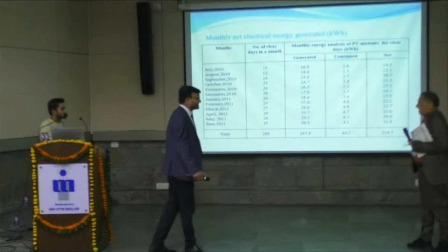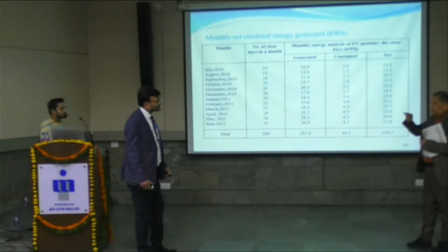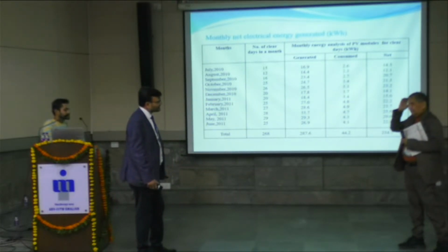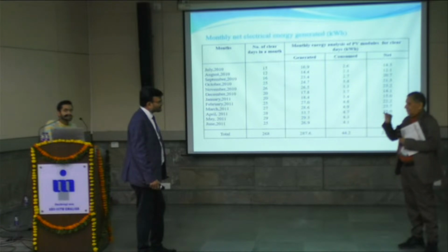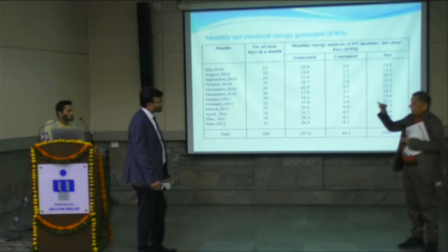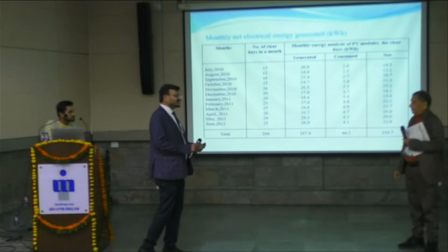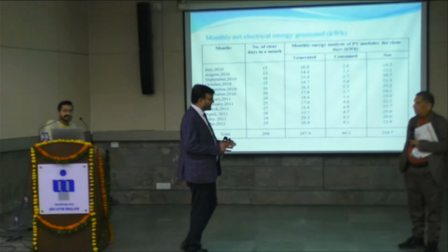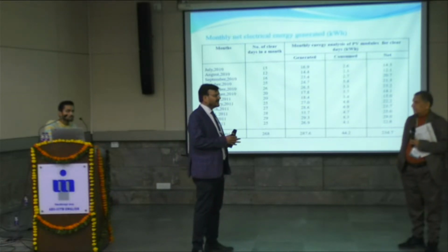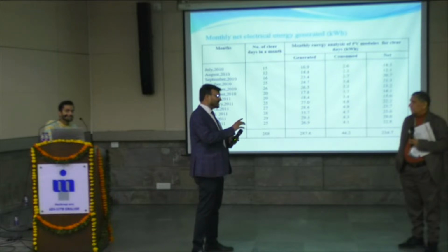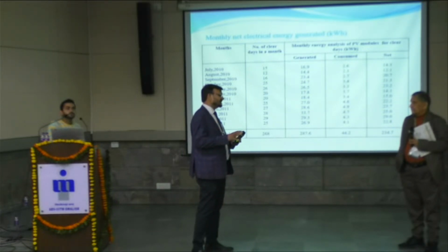Okay, good. Then another question is, have you seen for each degree increase in temperature, how the efficiency is affected? Efficiency, as the literature is available and experimentally validated, if 1 degree centigrade temperature is increasing, roughly 0.04% electrical efficiency is getting down.